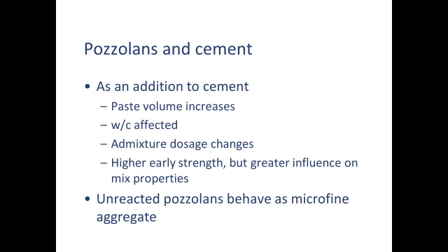But it's sometimes what can happen. Here's the scenario: you add too much pozzolan because you're boosting your cement paste and you're not changing your water cement ratio. All of a sudden the concrete gets stiff, and the common reaction is to add more water to the mix to boost the paste, get it more workable, and now your strength goes down because you've had to add more water. The proper thing to do would be to add more superplasticizer to the mix, but that can be problematic too, just by trying to dose it by eye, as I had mentioned before, with segregation and all that.